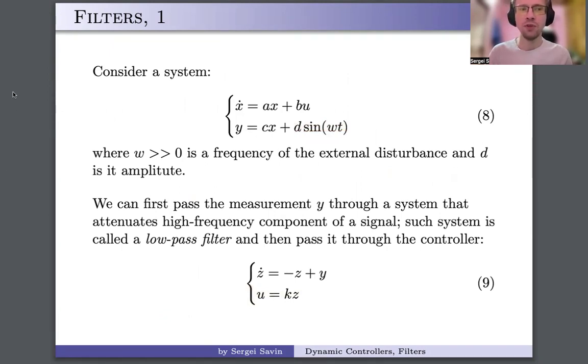For example, you could design a system which would delete, I'm using simplified terminology, forgive me, additional elements like this. Let's say you have an input which is static, just a static input, but you don't know what it is. You absolutely don't know what it is. You can design again a controller in this form, and that will be called a disturbance observer.